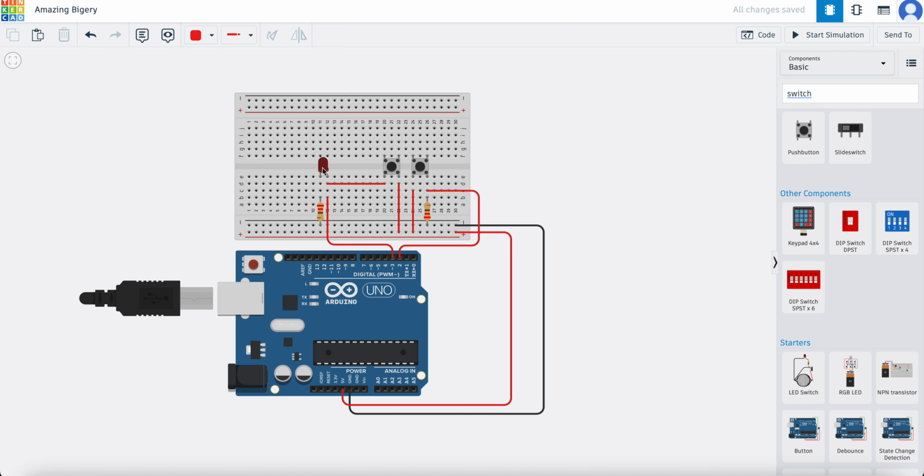Now our breadboard isn't quite big enough, so we're going to need to make a little modification here. We'll drag that over there, and we'll now connect the output side of here to our LED. Okay, now between here, we still need to connect pin number 3 because I still want my program to also work. I want to have the option of either using the software program, but if the computer's crashed, I want to still be able to physically override and turn on the light.